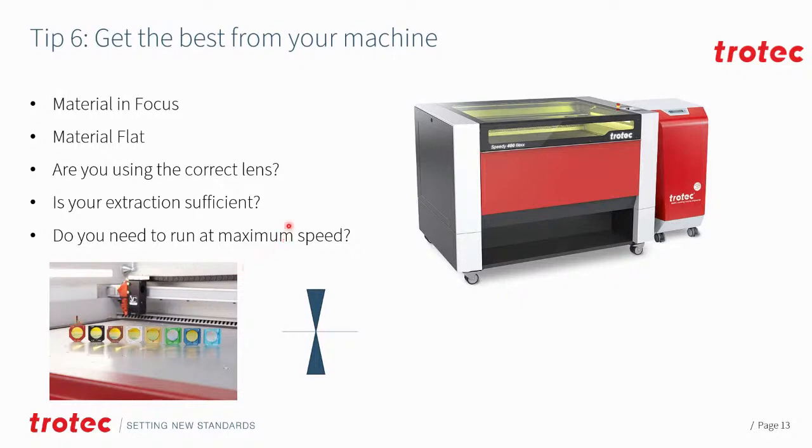Next up, you also need to consider, is your extraction set up and is it working well enough around the engraving. So if you think we're engraving a layer of the material, if you're leaving dirt and debris on the rest of the material that's yet to be engraved, the laser not only has to mark the material, but also now has to remove the debris that's been left on top. So make sure that your extraction is set up sufficiently.